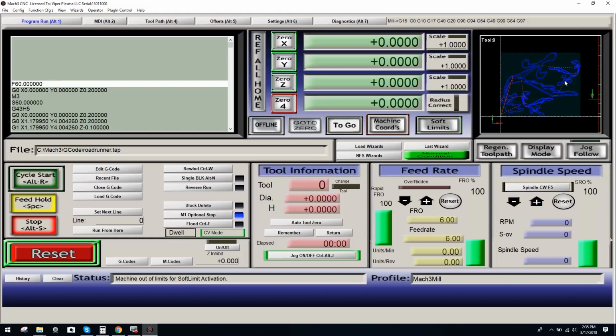There's no more graphic representation of the actual gantry, and it will come back once again once we actually regenerate our toolpath. But what you'll notice now is that if we hit machine coordinate and we hit machine coordinate again, when we're in G54, it's at 0. When we hit it again, and now we're representing the distance to the end stop of the table, you can see you're also in 0, which means now we're set.